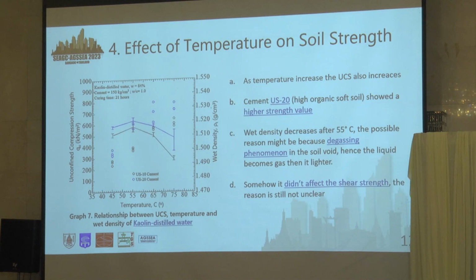But we can see here the wet density is decreased. One possible reason, after 55 degrees Celsius, might be the gassing phenomenon inside the soil void. As the liquid becomes gas, it becomes lighter. Somehow, it didn't affect the shear strength. The reason is still unclear.